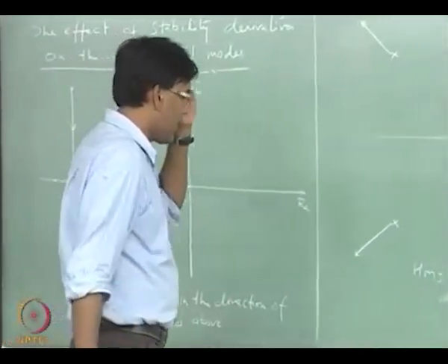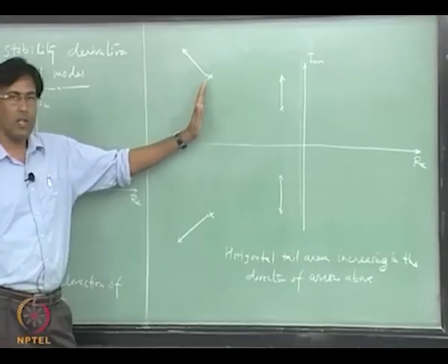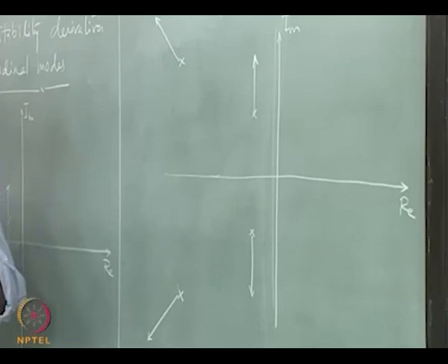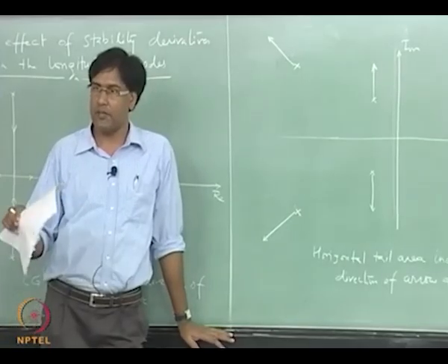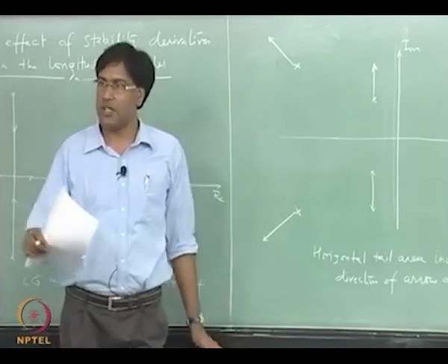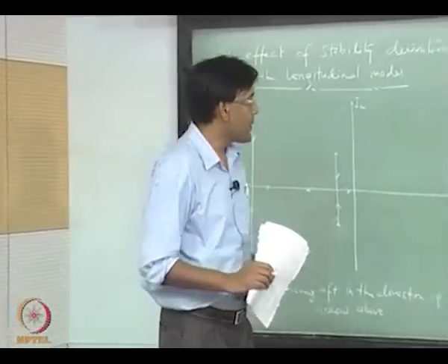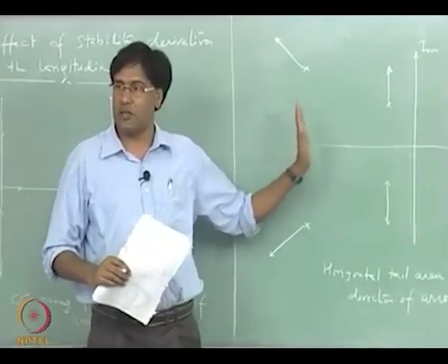So the problems associated are these. If the damping is low in short period, then controlling the motion is going to be difficult, right. Low damping in any motion is going to be difficult to control, right. Phugoid, this is related to the pitching motion.